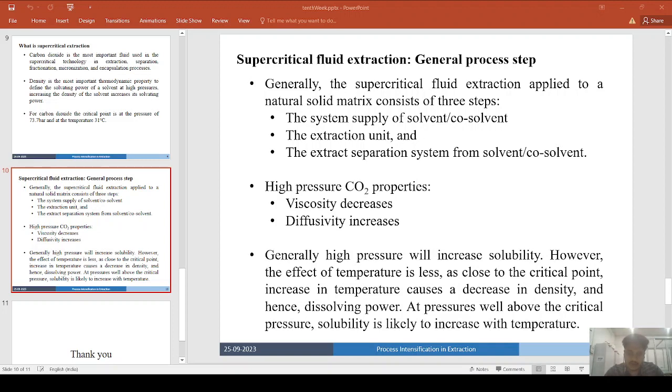The solvent is fed into the extractor and evenly distributed at the inlet of the fixed bed. The solvent and the soluble components leave the extractor and feed the precipitator separator, where the solvent and products are separated by expansion, by depressurizing. Since at low pressures the density of the solvent sharply decreases, it decreases the solubilizing power of the solvent as well, and the product precipitates.